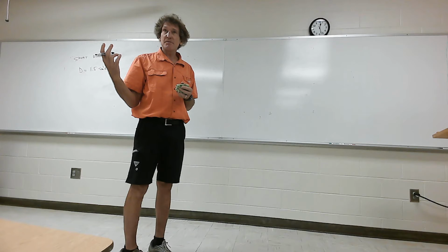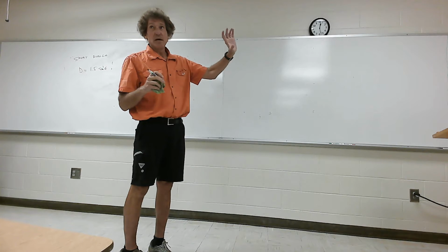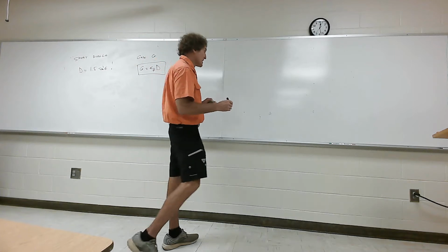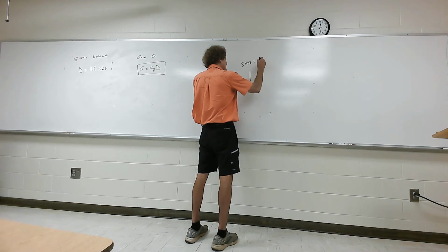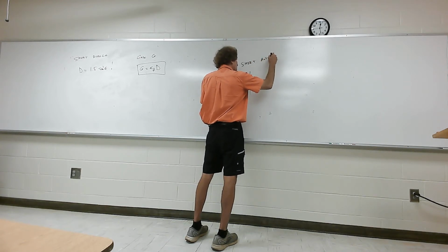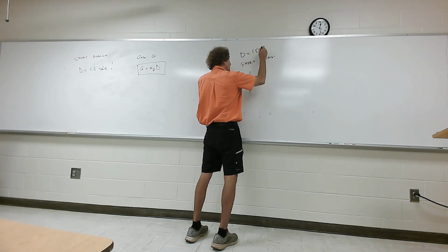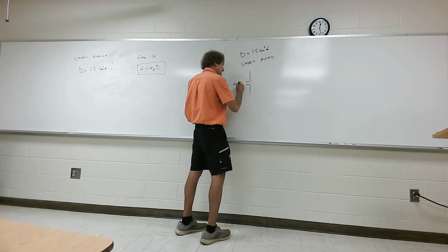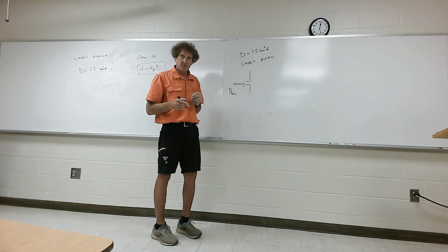So anyway, now how is this useful? I'm going to show you how this is so much better than so many other things, like calculating those E field equations just for a short dipole, which is a whole lot of j, eta, betas, and all that stuff. All right, so here's something. If I have an antenna, let's use a short dipole, but it doesn't matter what kind of antenna, and I have the directivity. For a short dipole, it's 1.5 times the sine squared of theta. Now, if I know I'm transmitting a certain amount of power, I'm going to say the total transmitted power is P-tran here in watts. You okay with that?